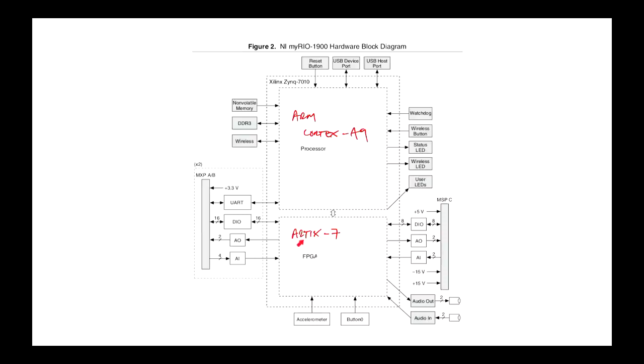You'll be programming this with what's called a fixed personality. It's already got all of the required logic to deal with serial ports, analog and digital inputs, audio, accelerometer, all that sort of stuff. You will be primarily focused on programming this and reading the sensor data through it. As I said, it's a really cool architecture: two in one, an FPGA and a more standard microcontroller.